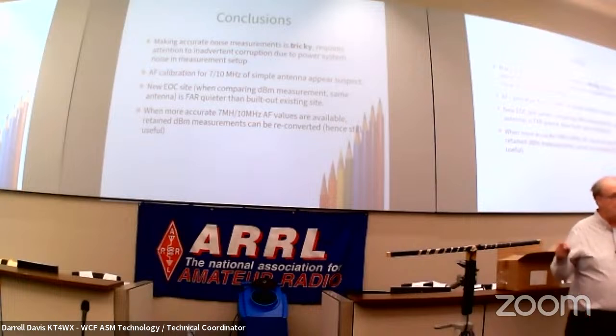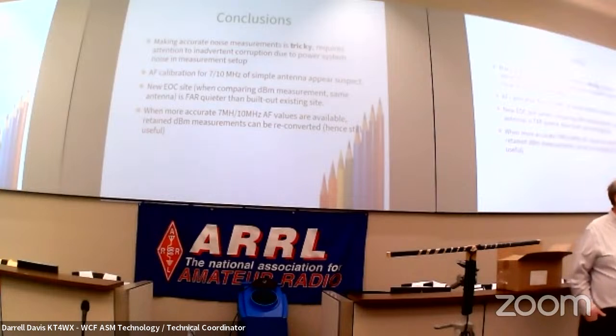But if you're smart, you make one of these measurements before you have the system installed. And then you do it again and see what happened. And you say, well, hey, you didn't do it. So I want you to add more filters until you get this thing quiet, because I want my radios to work.